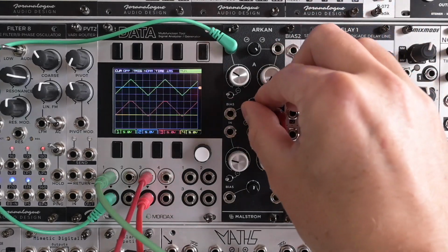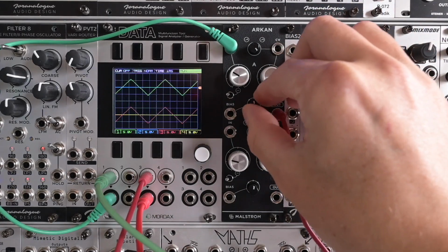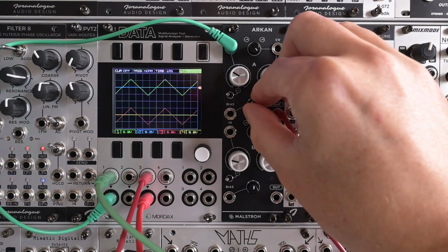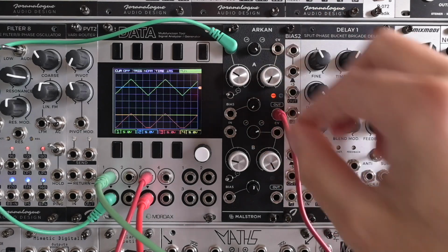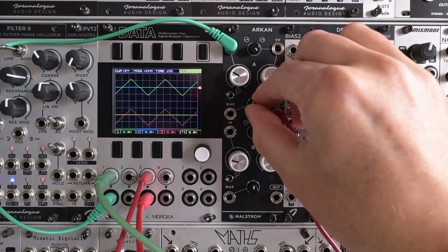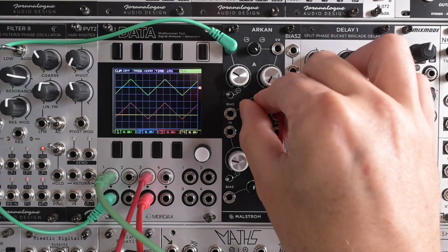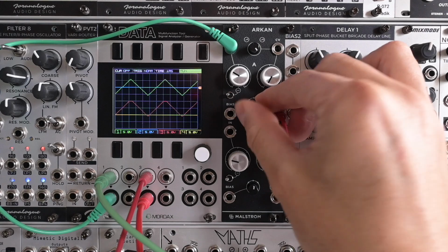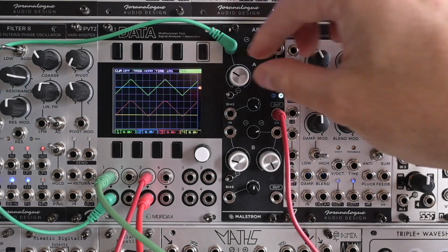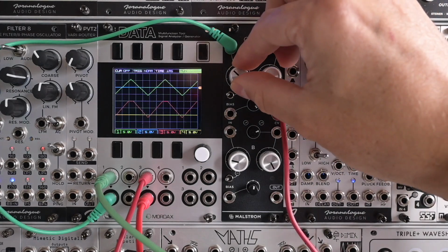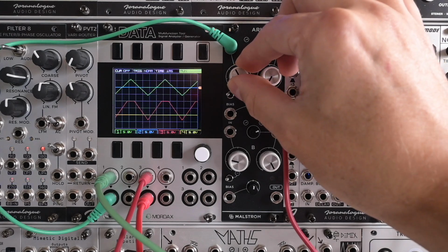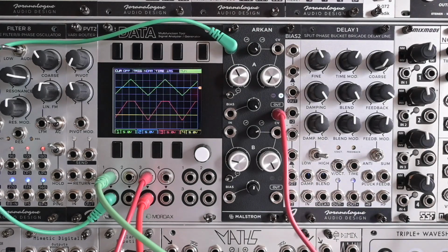Alternatively, turning it to the left adds an offset of minus 5 volts. And you can see that at its edges, again, we can see some clipping of our wave. This is even more so when I turn up the amplification at the input stage. And the thing we are seeing right here is asymmetrical clipping.